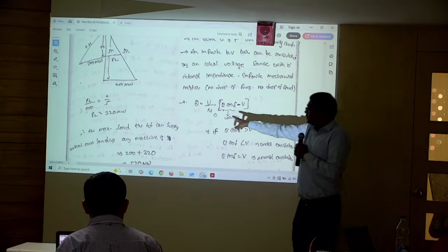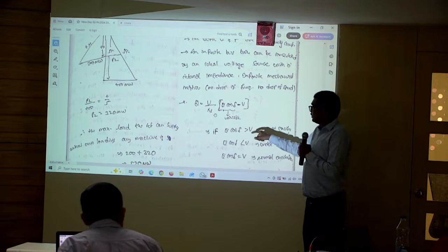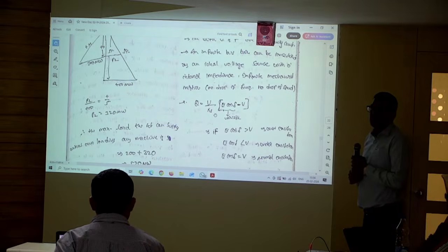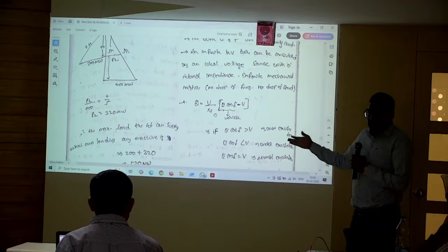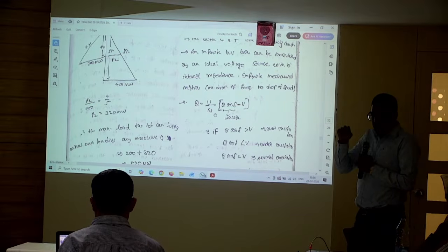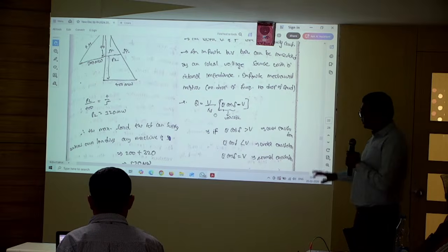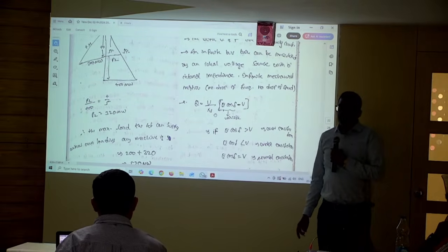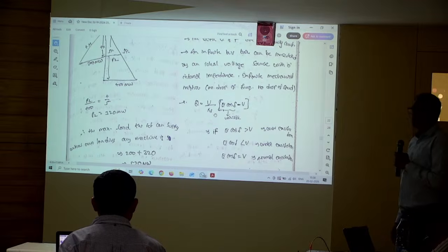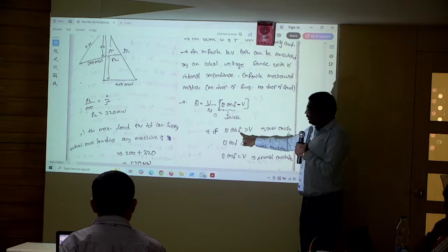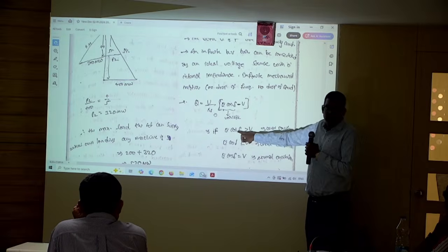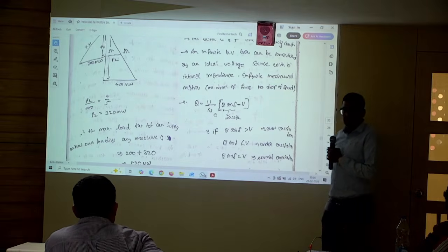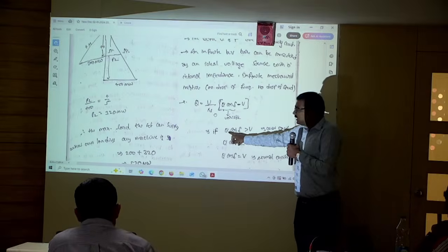Now, Q depends on, if V is constant, say delta is equal to constant. Delta means load angle. Ideally, for an infinite bus bar, because of its stiffness in mechanical inertia, delta is close to 0. When it is close to 0, Q is directly proportional to E cos delta. If delta is 0, cos delta is 1, so reactive power is directly proportional to the EMF generated.